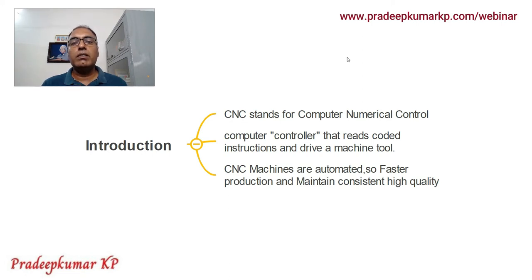So the computer does the job of creating the NC codes according to the design file supplied, and whatever way we have programmed in the CAM software, that is, what all tools we have used and how much depth of cut we have given and various other machining parameters and tool parameters, accordingly, and according to the design it will create a tool path.